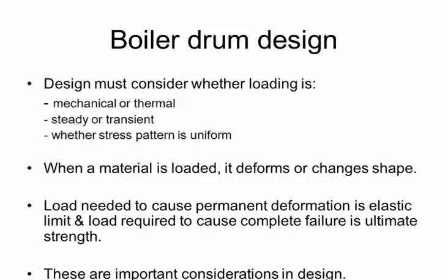Drum design continuing. The design must consider whether loading is mechanical or thermal, steady or transient, and whether the stress pattern is uniform. When a material is loaded, it deforms or changes shape. The load needed to cause permanent deformation is the elastic limit, and the load required to cause complete failure is the ultimate strength. Okay, so please mark this as well, because you will come back to this. These are important considerations in the design, so mark all these design ones.